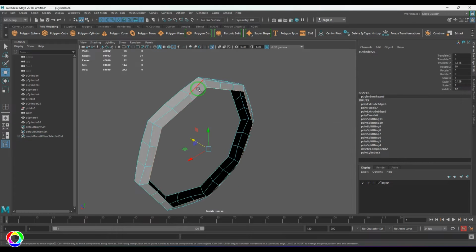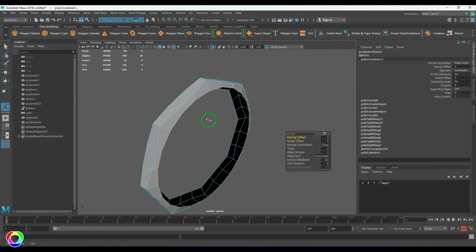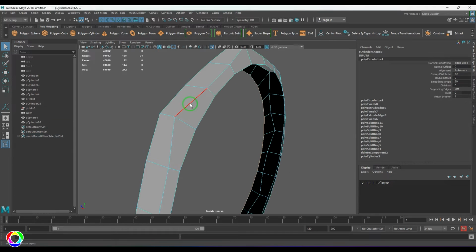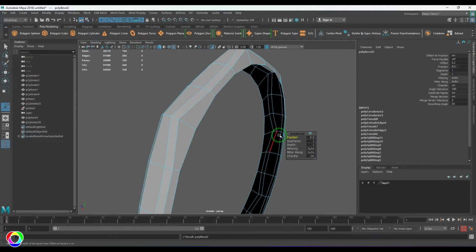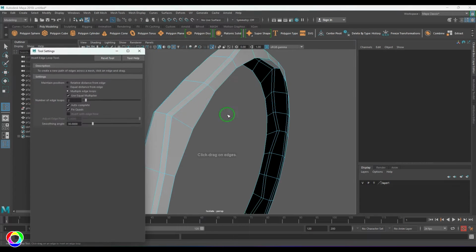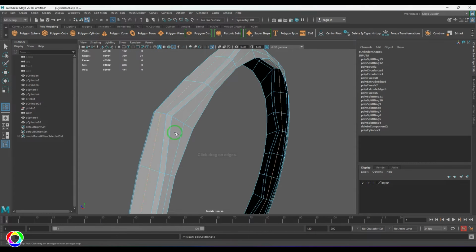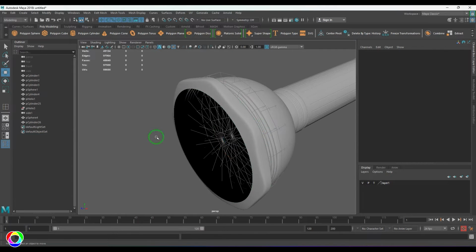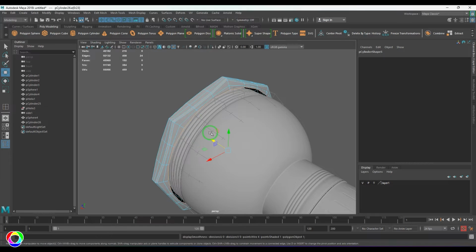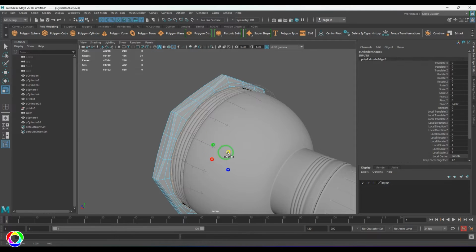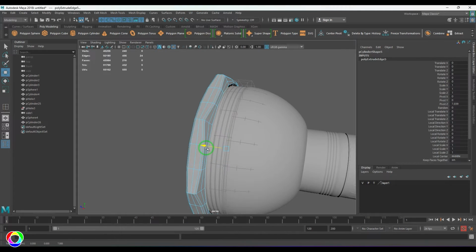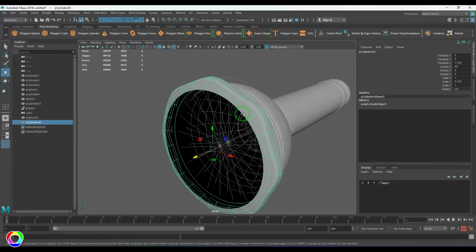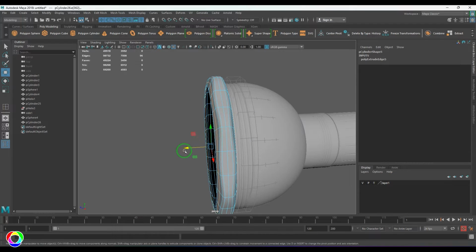Okay, make sure that it's straight for better visibility. Okay, I'm going to select this one and apply the circularize tool, and that should be fine. I'll be applying bevel and then use the insert edge loop tool, and then you should get that soft beveled model. Okay, and I'm going to scale this and move it like that, and I'll be not touching anything here.